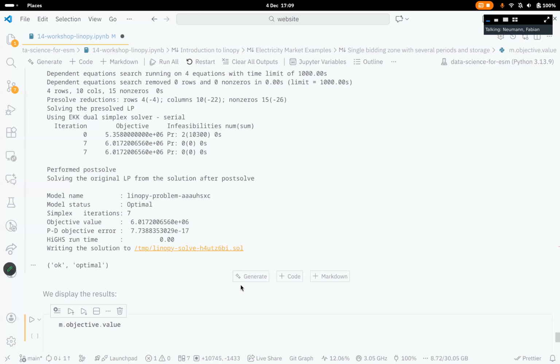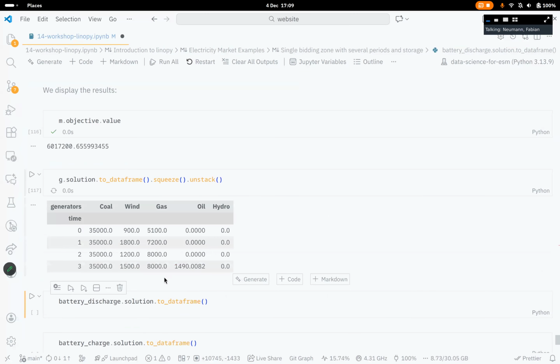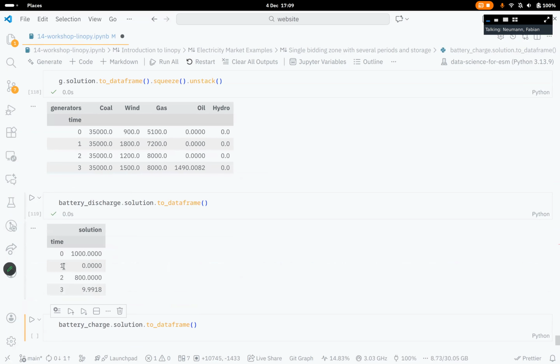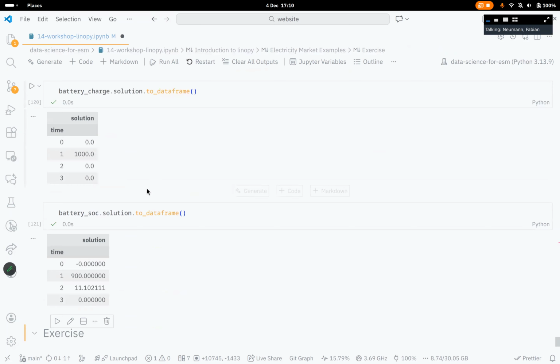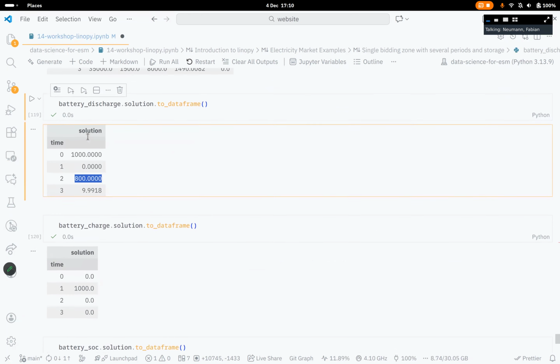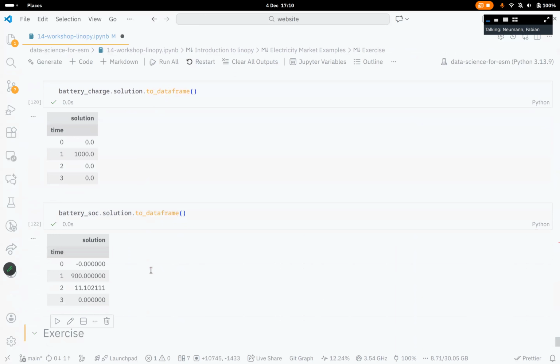So this we can solve, and now we should actually confirm the mistake that you discovered. You have the dispatch that's different than before because now we have a storage operation. We now have some curtailment values because we have some storage inefficiencies playing a role. So I think there's a bit of a mistake that in period 1, the dispatch decision that we take here doesn't end up anywhere. But we have some charging in period 1, and then some discharging in period 2, and a bit of discharging left for period 3 that we can see in the state of charge.